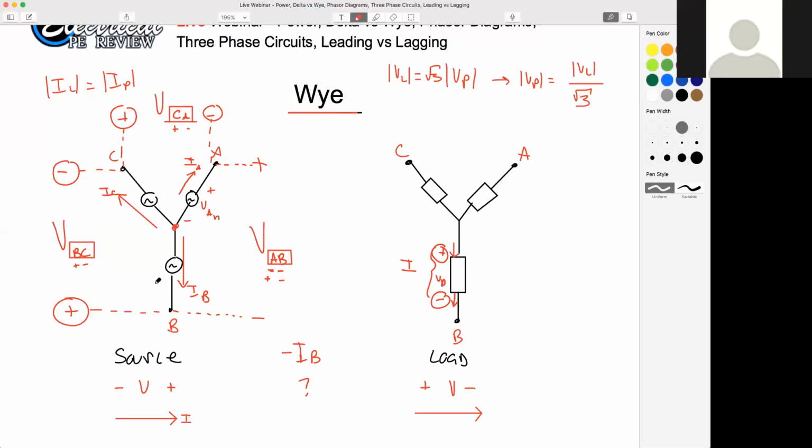Perfect. Yep. So really, is everyone comfortable with a negative sign? When we multiply it by a current, all we're doing is changing the polarity. And when we change the polarity, all we're doing is changing the direction. So that would be minus IB. Okay. Craig said along the B leg towards neutral. Perfect. Good job, Craig.